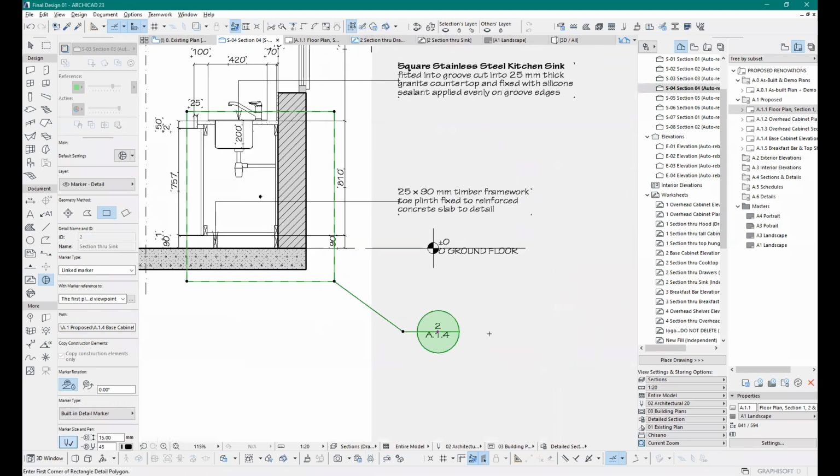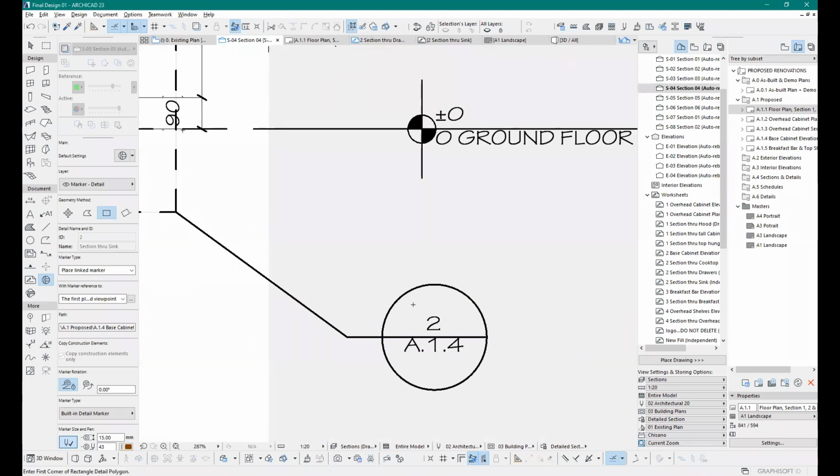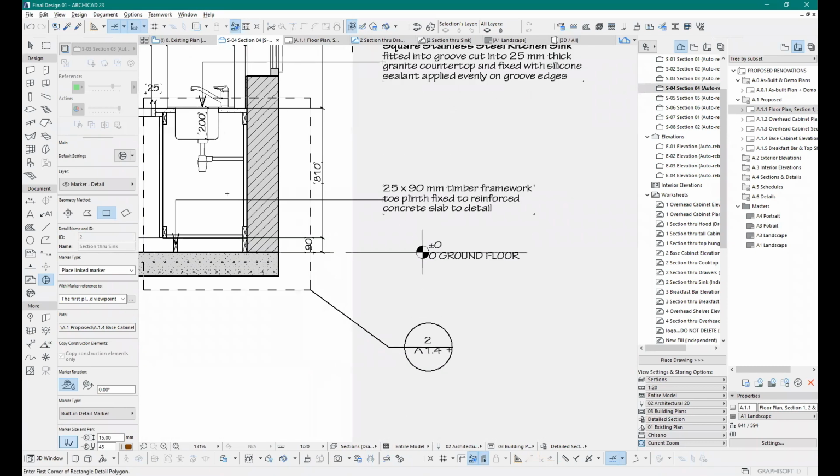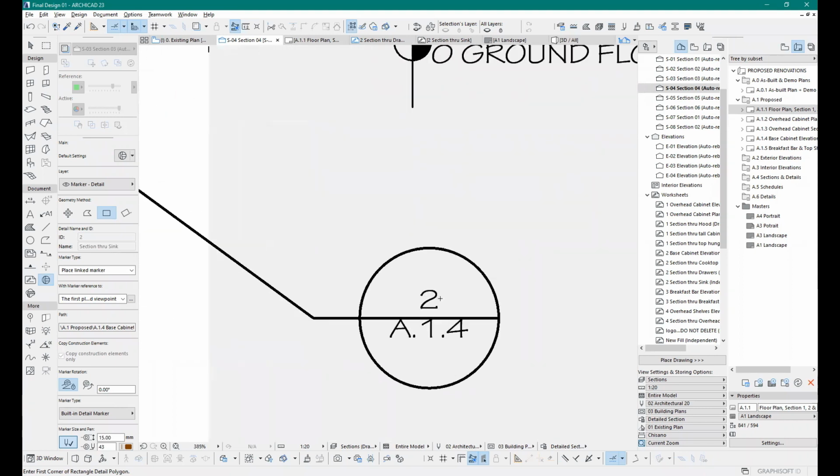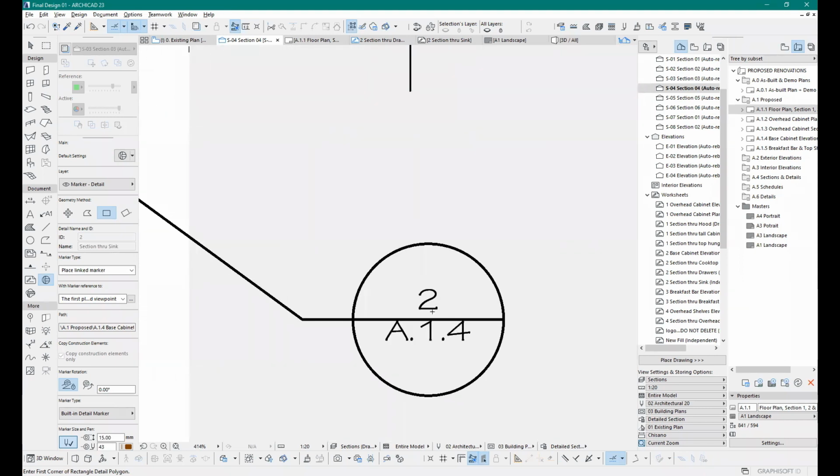So when looking through your construction documents, the way to quickly find information is using these numbers here, these two and this A14. If you look at my layout, you'll find that there's an alphanumerical tag at the start of this layout name. So there is A11, A12, A13, A14, A15. This is called a layout ID.